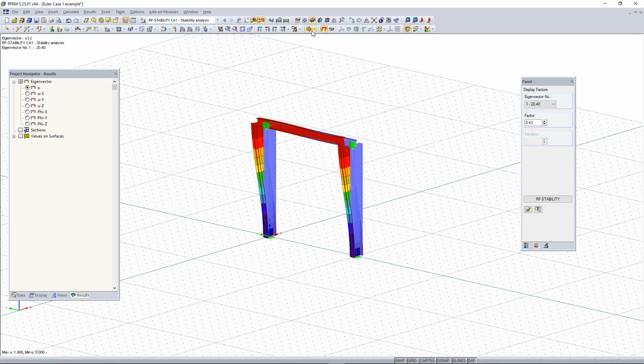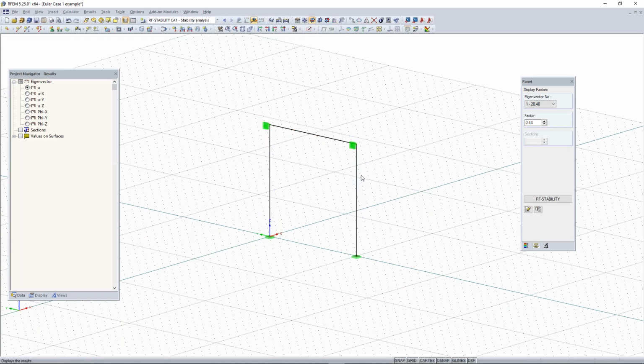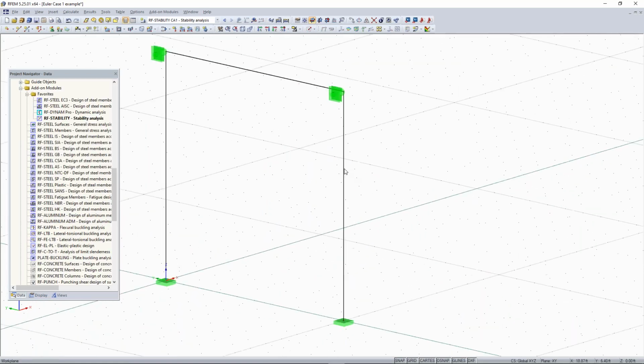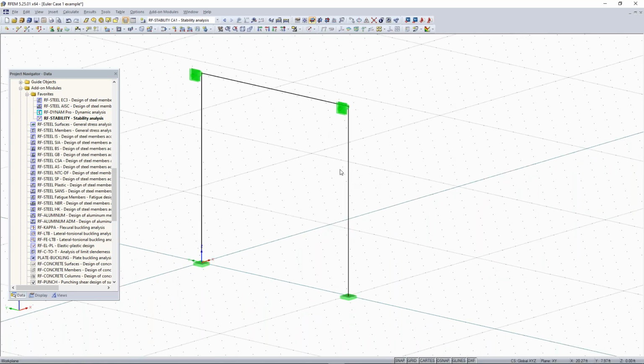So keep in mind, like I said, members in RFEM are only 1D elements. You have to make sure that the way you're drawing things within AutoCAD includes the center lines for the members, because that's the most important thing to have imported over. If you have just the actual shape drawn in AutoCAD, like the perimeter lines or the boundary lines, then all of those lines will be imported over and you can't really define the cross-section onto them.